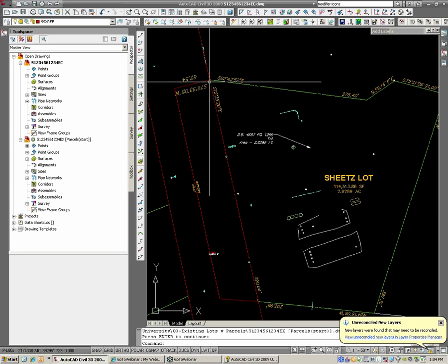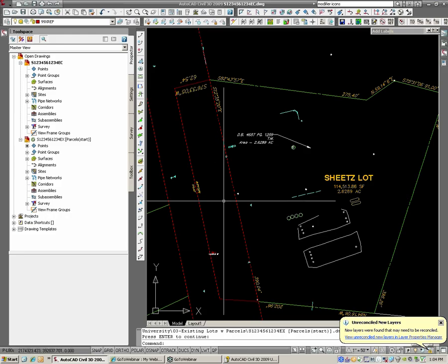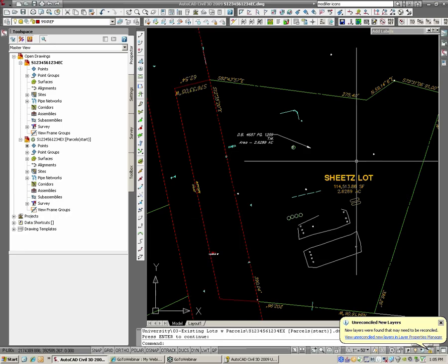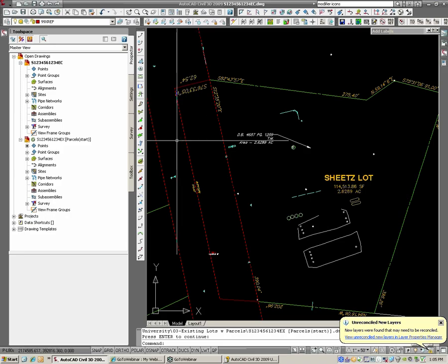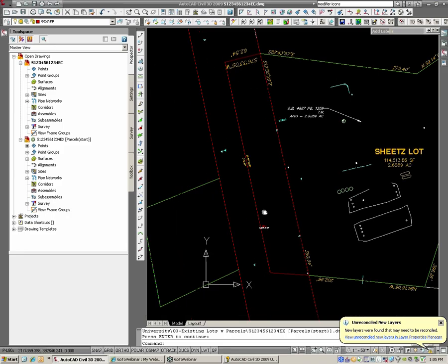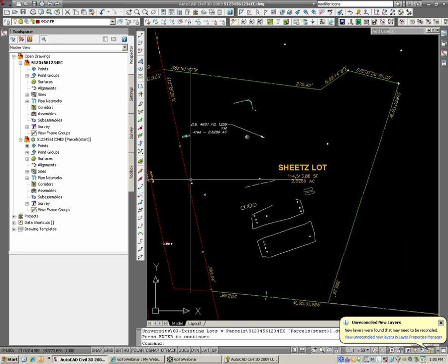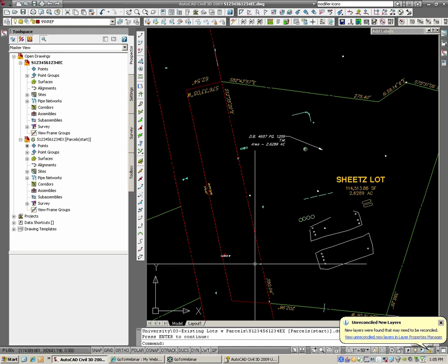The hardest thing you'd have is I don't know how I would get these lines to be green if I would make this into a parcel. They would have to be red. Actually, you could get them to be green by making up a third style. So you'd have property existing, property in right-of-way, and then right-of-way, and then you'd set property in right-of-way above right-of-way, and then property existing below that, and maybe that could turn these green. That would be a layer game for coloring. That would be my thing there.